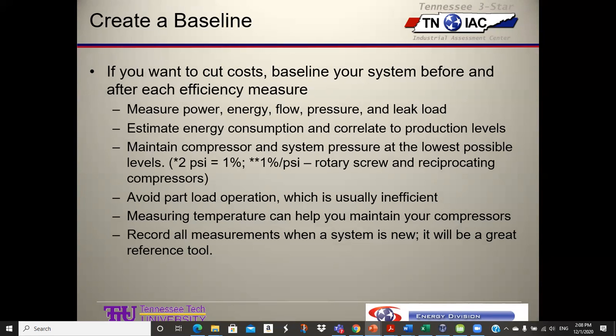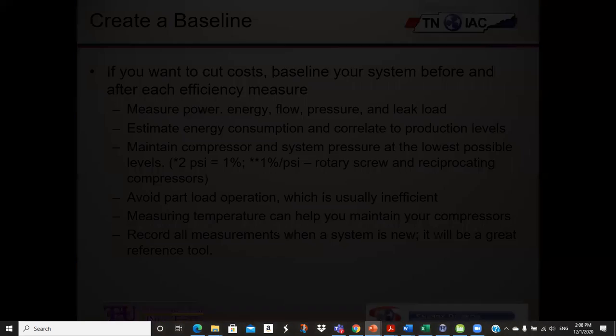Measuring temperature can help you maintain compressors. If temperatures start going up, then it could indicate a maintenance need. Could be a heat exchanger, could be a problem with the compression element, probably some sort of heat exchange situation. And record all measurements when the system is new, and it's a great reference tool. So you can say, well, we're running 105 degrees coming out of the package. What did we run when this thing was new? And the weather was the same. So you can go back and compare.